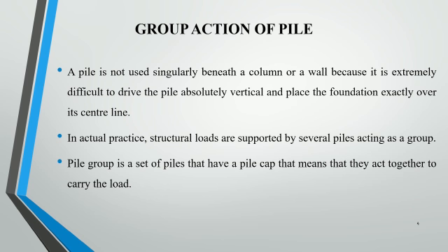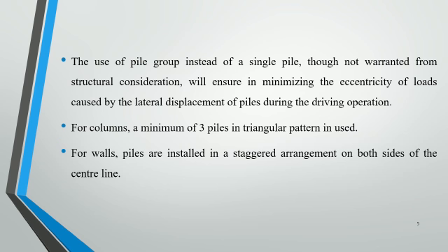Pile group is a set of piles that have a pile cap. That means that they act together to carry the load. The use of pile group instead of a single pile, though not warranted from structural consideration, will ensure minimizing the eccentricity of loads caused by the lateral displacement of piles during the driving operation.